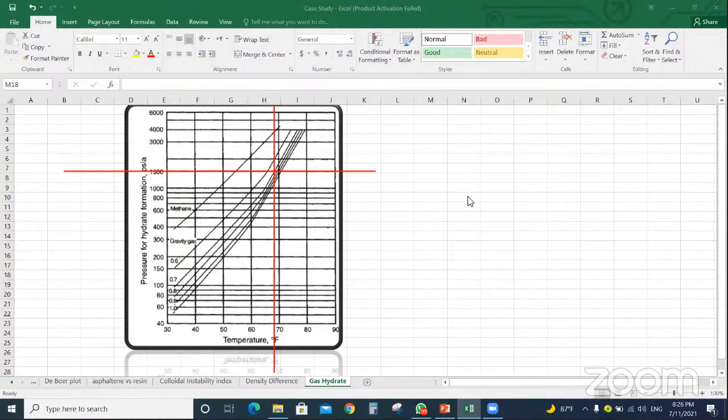Okay, we have another question. Please explain more about how adding light components destabilizes asphaltene, like mixing other oils with asphaltene. When we add some light components to a solution that has asphaltene, it will uncover the resin protective layer that covers the asphaltene molecules. So some colloidal action will occur between the asphaltene molecules that will lead to aggregation between them until reaching a critical mass. So the asphaltene in this case will be deposited.